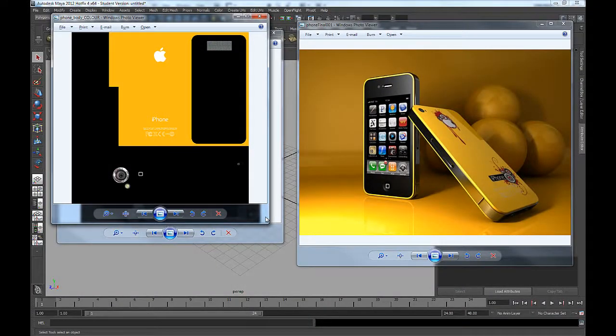Hi everyone, in this video we're going to take a quick look at some basic UV template systems. A UV template is a system that allows us to place an image onto the surface of a model with a high degree of accuracy. Essentially it lets us place things like logos, text, symbols, and just general coloration onto our models specifically.